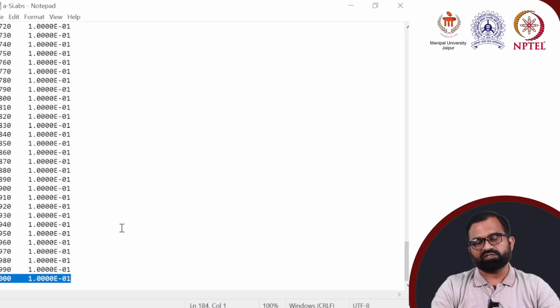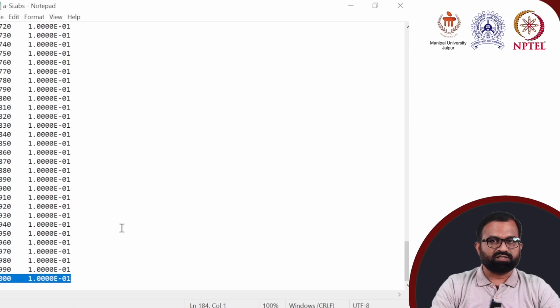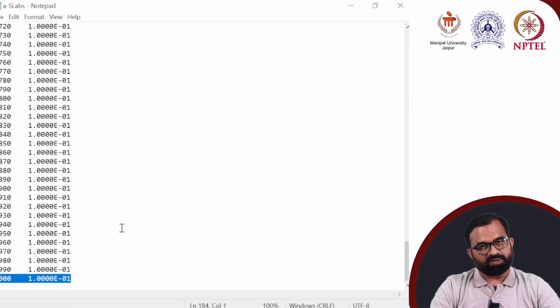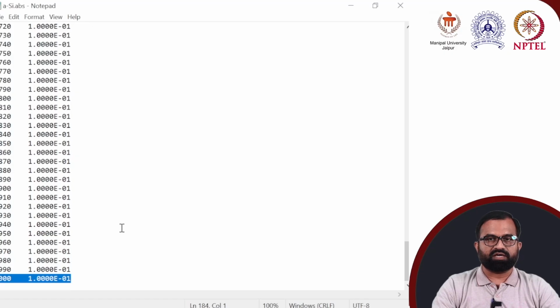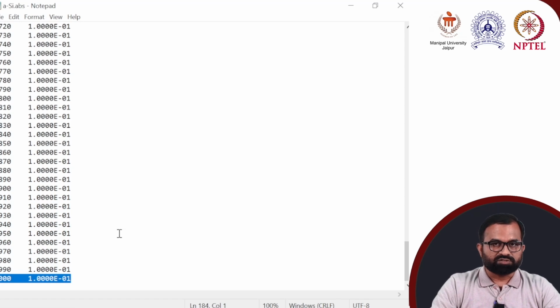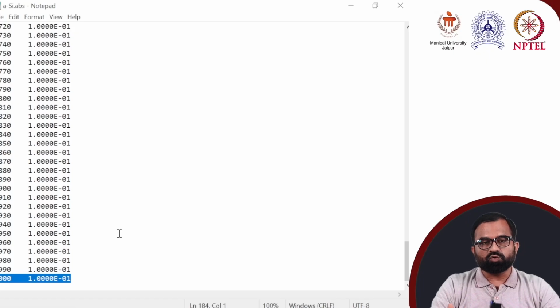So if the last reported value is at 700 nanometers, and the solar spectrum you have set goes up to 900 nanometers, then for 900 nanometers the program will get alpha by extrapolating the last value, that is at 700 nanometers. So it is important to close down the absorption data with the lowest value of absorption, in the order of -1, you can choose.